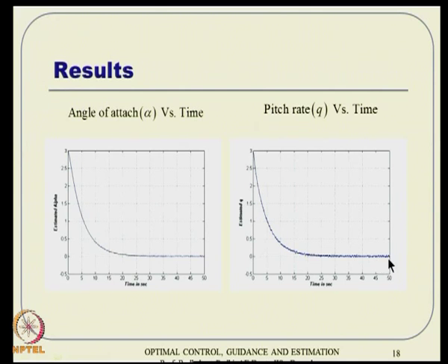But there is a small residual error, a very negligible residual error. The structural aerodynamic damping will take care of that and will not let you have this. So, do not worry about this small chattering here; in reality it will not happen. But even if you see these small residual errors on the way, they are smoothened out at the alpha level.